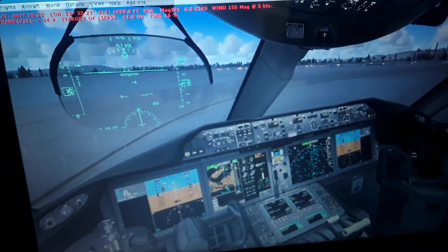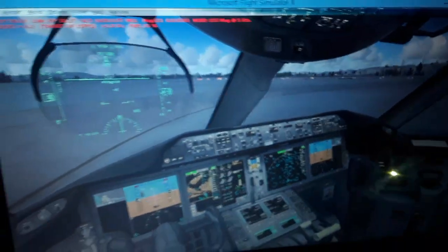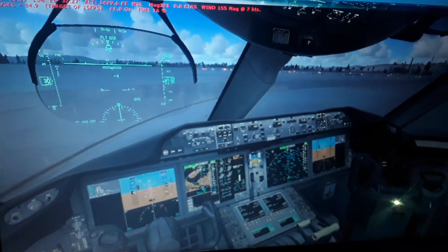Also, you can calculate the velocity difference between our aircraft and the other aircraft. It will give a warning if we have an incoming collision in the air or on the ground, so we will make an avoidance maneuver in the air using the TCAS, the traffic collision avoidance system. You can see the terrain map, as I told you, here with the airports. You can see the runways also when we create the flight plan. You will see the runway we're going to use for takeoff and for landing.